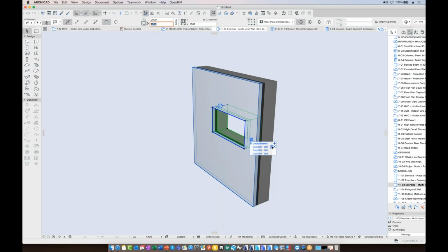And I think really what we'd want is just to have one opening rather than place three. The reason why is because we avoid data duplication, and mathematicians don't like data duplication. And also, there's a limitation in that IFC openings can only have one target.